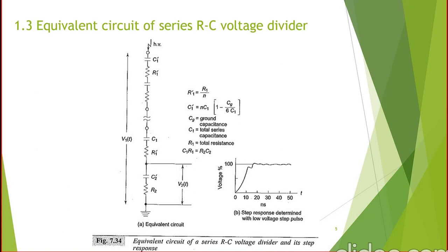Hello everyone, my name is Sayali Pawar. I am going to explain the mixed potential divider. It is basically a potential divider consisting of resistance and capacitance elements connected in either series or parallel. We are going to use the RC potential divider for improving the step response. The main purpose of it is to enhance accuracy, and furthermore it obeys the voltage division law.